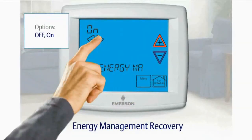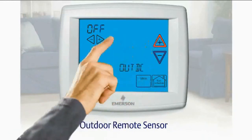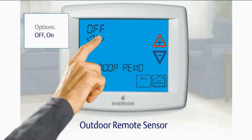Item 7, energy management recovery. With a selection of on, the system will start temperature setback recovery early to reach the program set point at the program start time. A selection of off will start the recovery period at the program start time. Menu item 8, outdoor remote sensor. A selection of on enables the display of the outdoor temperature.